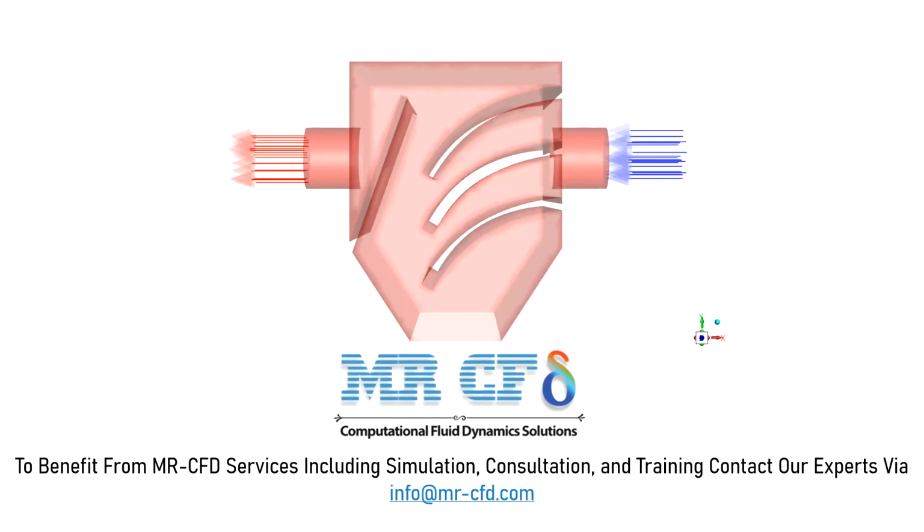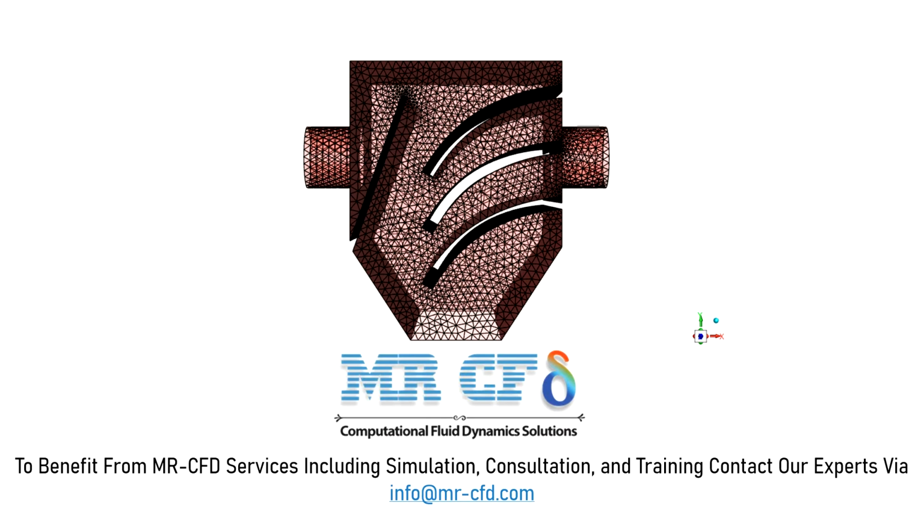The geometry which you can see in this slide is designed in ANSYS DesignModeler software and includes an inlet and outlet on each side of it. The mesh type used for this geometry is unstructured, and the element number is equal to 420,485.